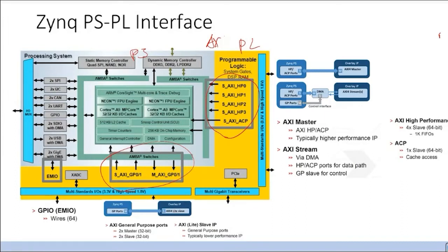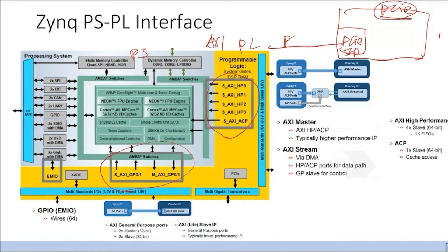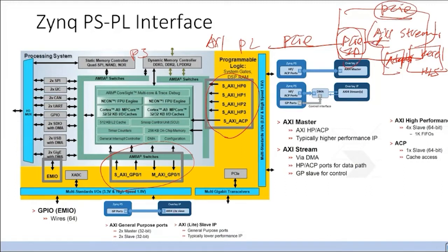For the PCIe acceleration card, you have the PCIe IP, which is a PCIe bus. All the data transfer has to go through the PCIe IP, and this PCIe IP is also an AXI interface, mostly an AXI-Stream interface. So when you design this kernel from HLS, you also need an adapter, just like in lab 2, to hook onto the AXI so that all the traffic goes onto the PCIe bus.